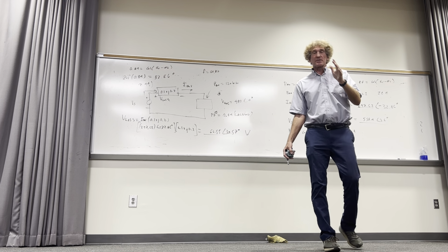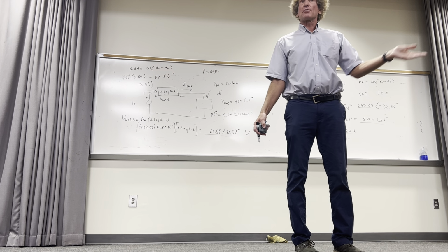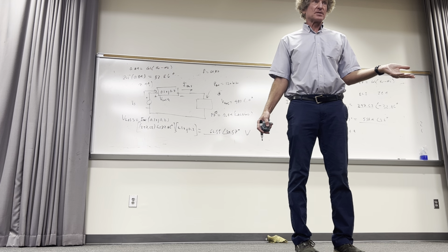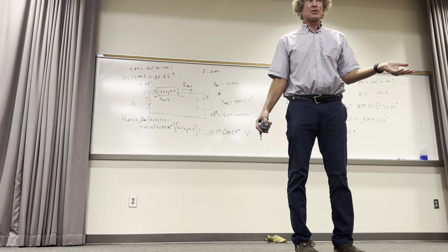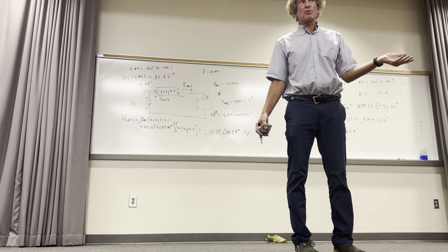And in this case, the voltage is at 0 degrees. If it is lagging, then your current angle is less than the voltage angle. If it's leading, the current angle would be greater than the voltage angle. That's the way you do it. If you do a bunch of problems on this, you won't mess up. But that's the secret to this stuff.